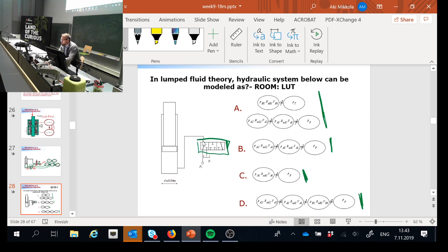Okay, so look at that. I have this direction valve, and now the question is associated with the fact that the direction valve is having this operation condition, not anything else except this operation condition. And what it means is that in this operation condition, the pressure source is connected to this one-way cylinder.